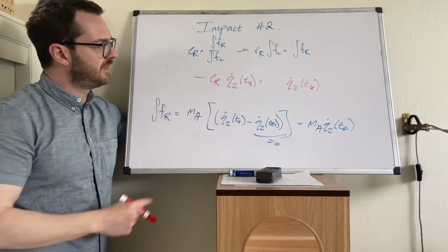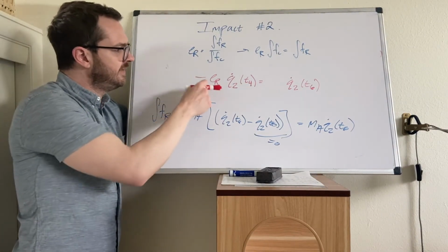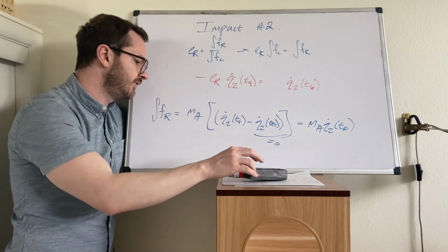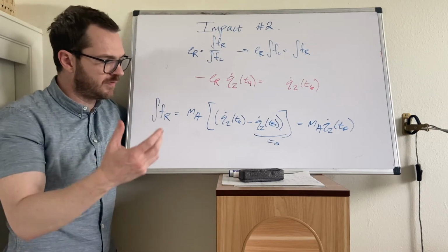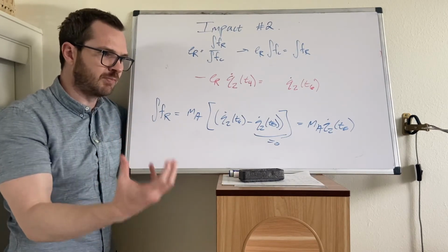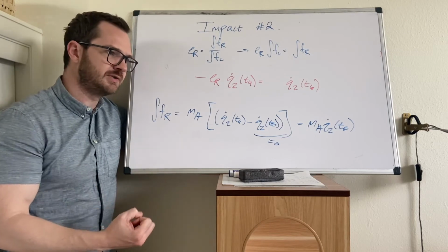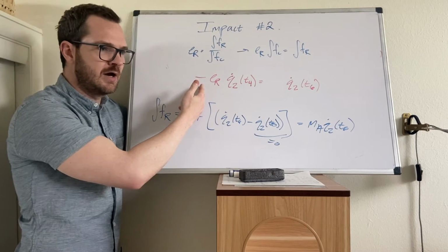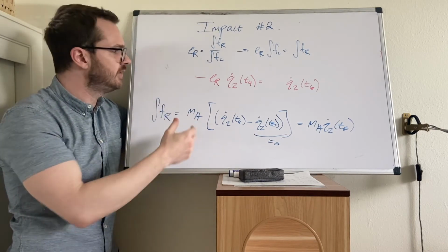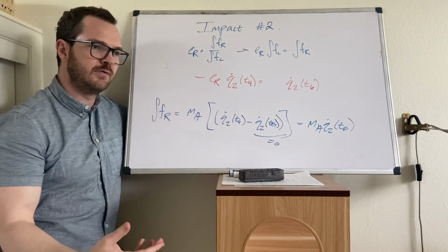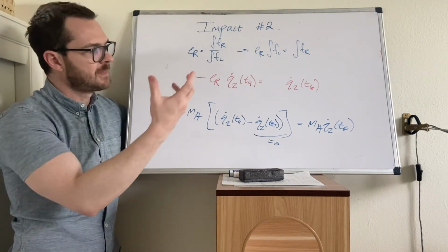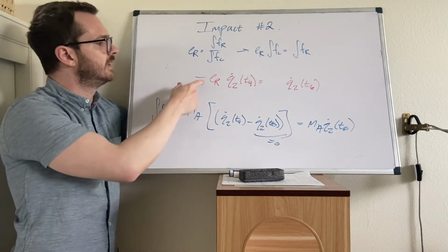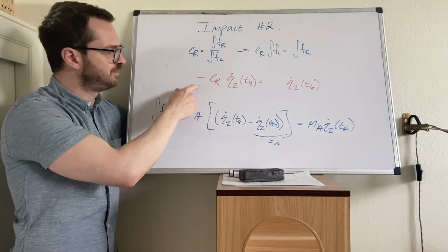Now, one comment about this E sub R. This could be a different E sub R than the first bounce, depending on material properties and speed. If it were, for example, a tennis ball, it is a compressive body. The rate of compression is going to change its internal damping. So you could have certain energy loss at high speed. You could have different energy loss at low speed, or depending on the geometry of the ball, right? If it hits on a certain side, if it hits on a different side, etc. So these values can change.